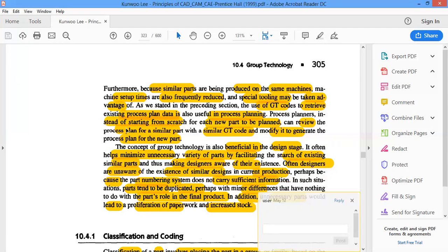With that same thing, we can have this data fetched from the 100 cc, make the required modifications for the 125 cc engine, and run these tests in a similar manner, whether it's the structural test, thermal analysis, vibrational analysis, and check for the relevant details like stress, strain, fatigue life, and all those things, all the design tests.